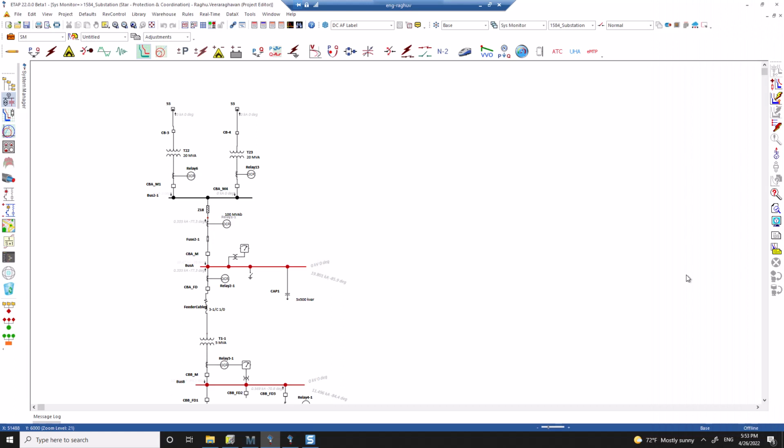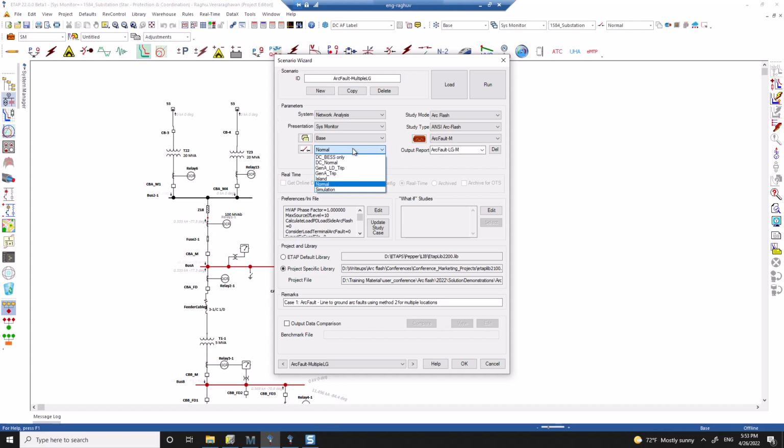Another feature that is available in ETAP that is commonly required for performing several scenario modeling, such as normal mode, maintenance mode, or using a different transition such as open transition or closed transition or main-tie-main, can be easily achieved using the scenario wizard. So where we can have a normal situation or a loading situation, or having different revisions as found settings or the recommended settings, depending upon the different ArcFlash scenarios that can be created. So that would help us to get a different set of combinations and evaluate the worst case incident energy respectively.